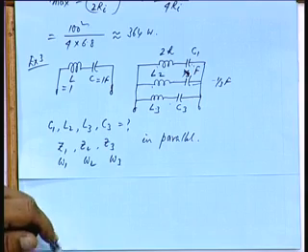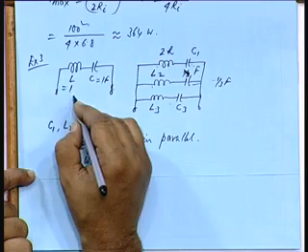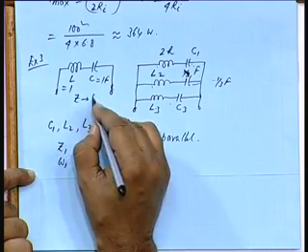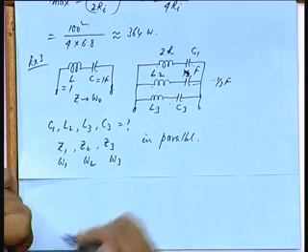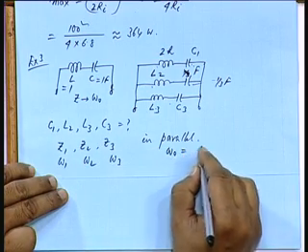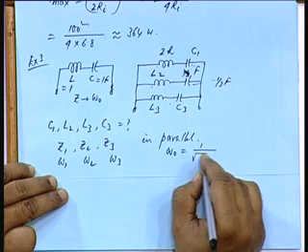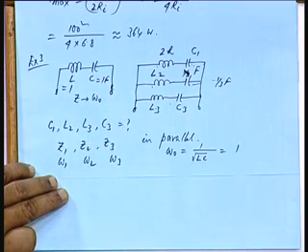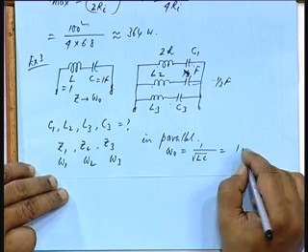Okay. At resonance, and similarly for this the impedance is say Z and corresponding resonance frequency is say omega naught. How much is omega naught? 1 by root L C, that is equal to 1, because L is 1, C is 1, okay, 1 radian per second.